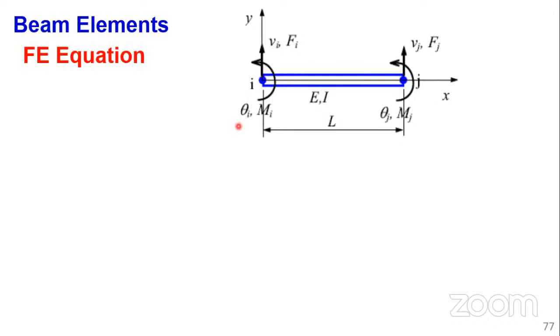You have to note that, of course, action brings about reaction. When you apply a nodal force in a member, an external force, you expect axial deformation to be associated with the axial load. In this case, moments are the ones which bring about the rotation, and vertical displacement is associated with the applied force, which can also be the reaction. So that's why these quantities are grouped together with how they are related: rotation related with the moment, vertical displacement related with the applied load.